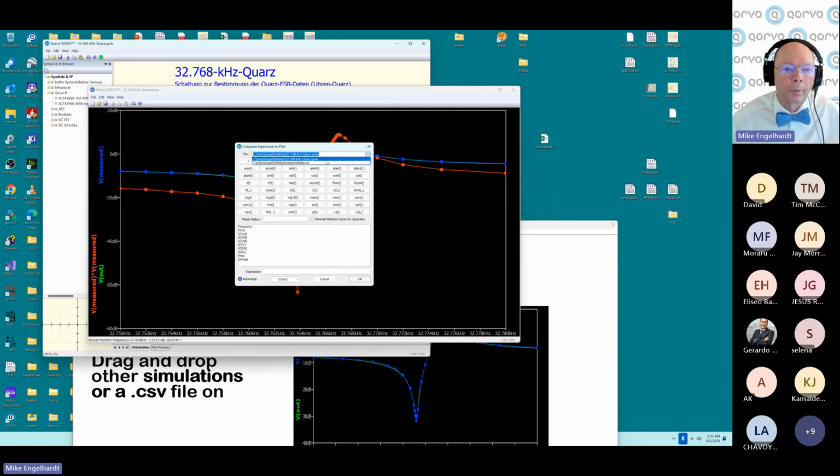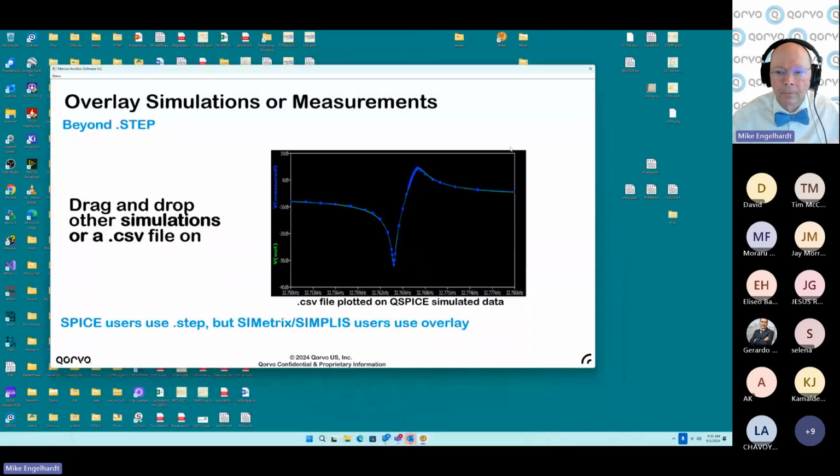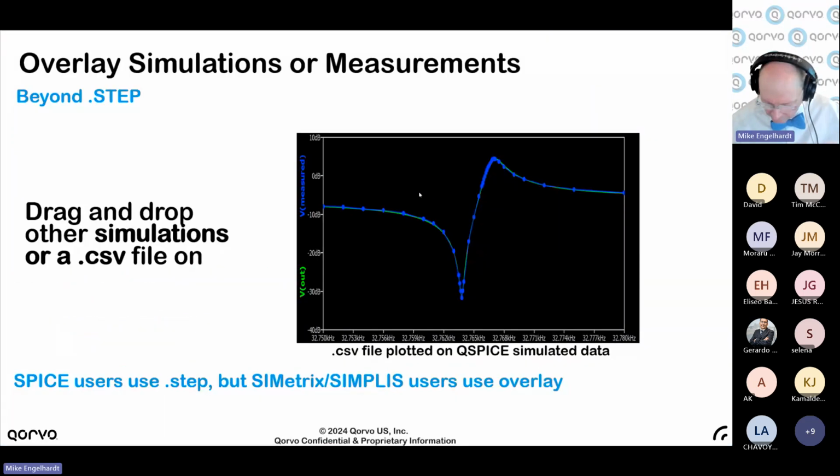You have to say which waveform you're referring to. Okay. So that's really useful. I use it a lot when curve tracing waveforms and then making models or correcting device equations so that the simulator can work like the real part.